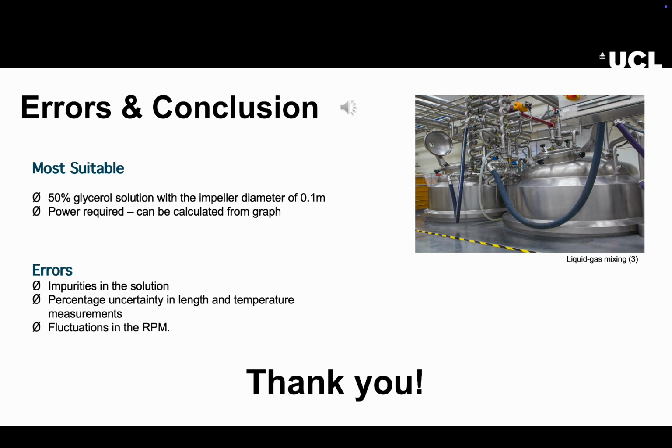However, it's important to note that there are a few potential sources of error that could affect the accuracy and reliability of this experiment. These include impurities in the solution, percentage uncertainties in the measurement, and fluctuations in the rotational speed. In conclusion, dimensionless numbers like the Reynolds and the power number obtained from lab-scale experiments play a key role in designing scale-up processes. Thank you for listening.